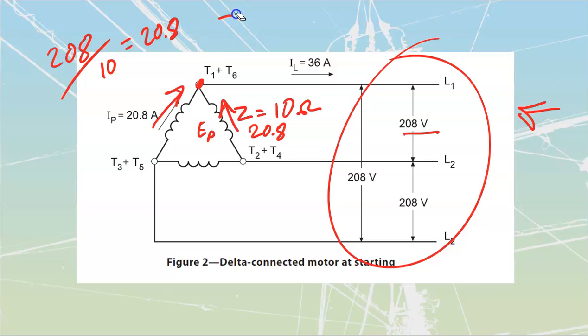So we could figure out what our total amount of watts would be that we would be delivering out of this thing. Now, I'm not going to go too far down the watts path. We can come back from the watts path for a second, because when we're looking at the watts, we are going to see different amounts of power out of our delta compared to our Y. Now, we understand that we're doing reduced voltage starting, not actually reducing the line voltages that we have over here. We're just reconfiguring the load, so it's going to react differently. And I'm not really that concerned about the value of watts that I'm going to have out of this motor at full delta compared to startup Y.